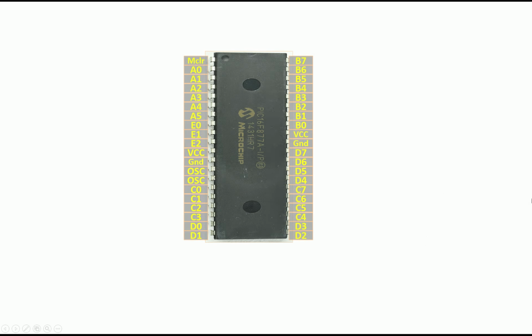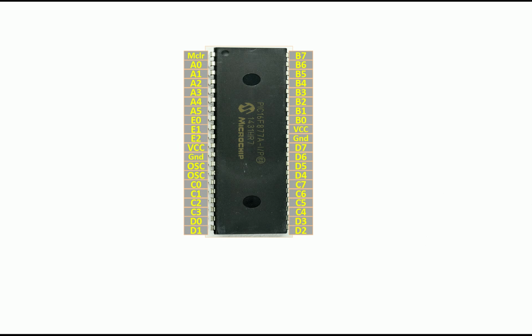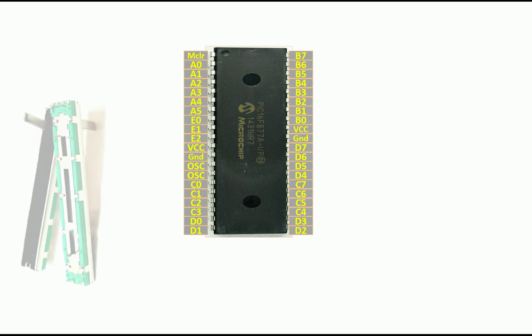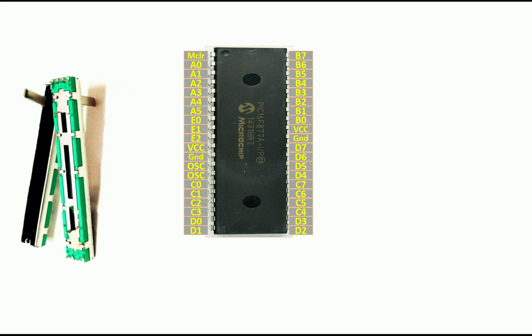Now guys, this over here is a PIC16F877A microcontroller having 40 pins. It's a DIP version. This on the left is a slide potentiometer, and as you can see, we have 6 pins, 4 at the top, 2 at the bottom. Now the bottom right pin is our VCC. The top rightmost pin is the ground. The second from the right from the top, if you hold it like this, is the ADC pin. The rest of the 3 pins will go empty. You do not need to connect them.